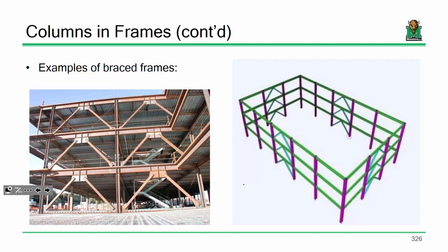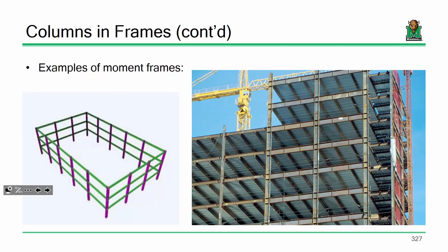Okay, so here's a typical building, right? So let's say all we're talking about is wind. Well, this building, looking at the way it's proportioned, can handle winds coming like this, like that, and like that. It can handle winds coming from all 4 directions because I've got bracing systems along all directions. You need something similar for every other building, right?